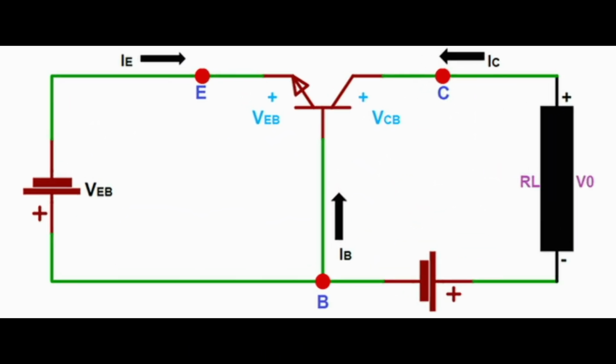Working of transistor, BJT. Practically the working of a transistor is very simple. It can be used as a switch or as an amplifier. But for basic understanding, let's start with how a transistor as a switch works in a circuit. When a control voltage is provided to the base pin, the required base current, IB, flows into the base pin which is controlled by a base resistor.